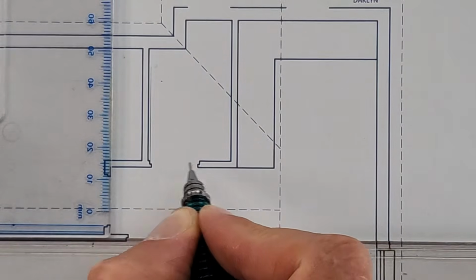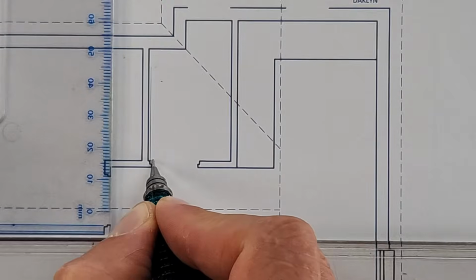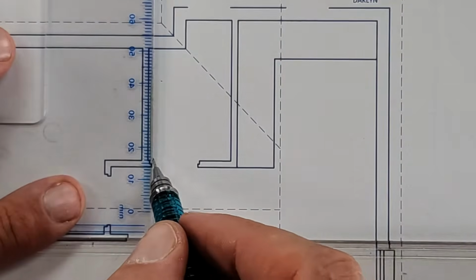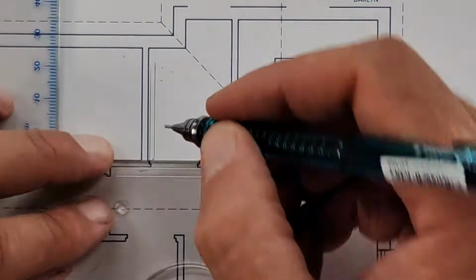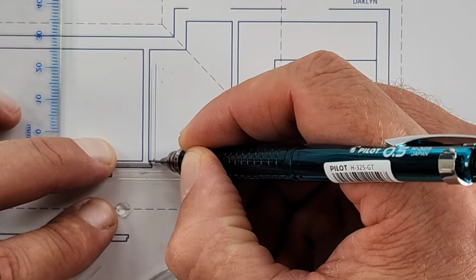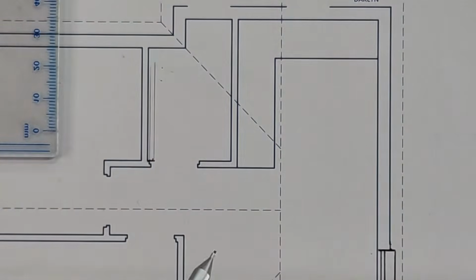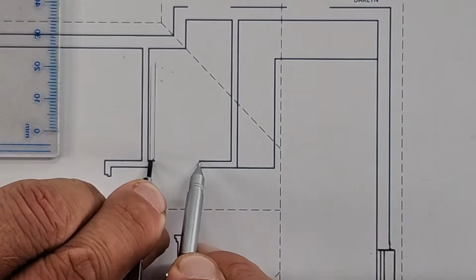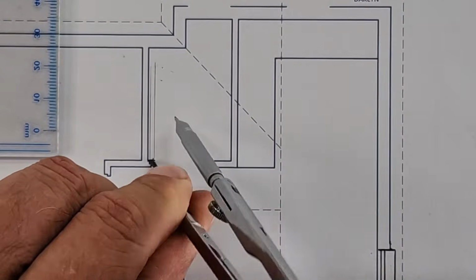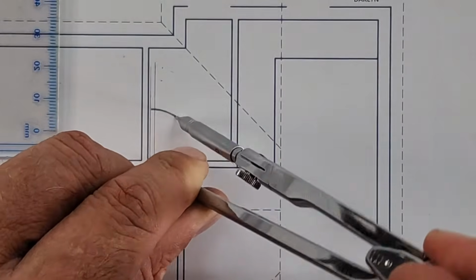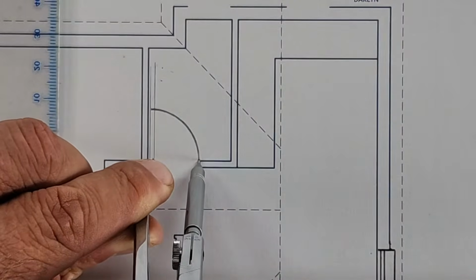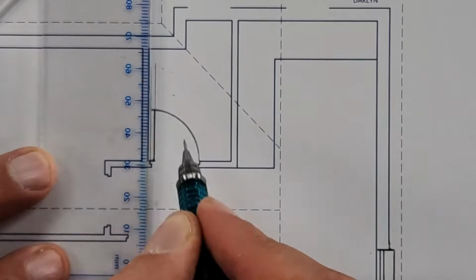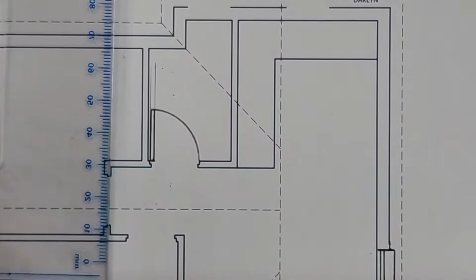Then you give it the same width as that depth, because that door, when it's closed, is going to fit into that gap, okay? So it's just 1 or so millimeter longer construction line, okay? There we have a corner on that corner. And now I take my compass and I set it on that corner, and in line with this corner, because it closes in there, I draw my arc. Okay, and I stop right there at that end. And now I go chip, chip, and my door is done.